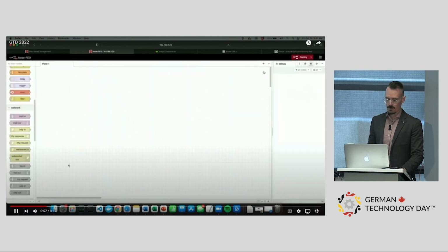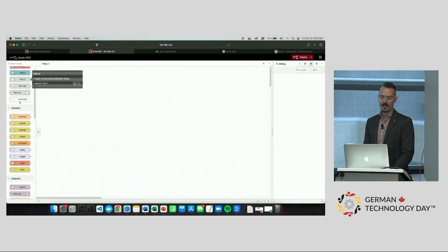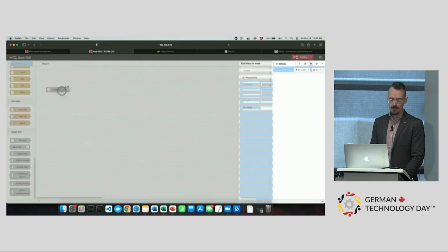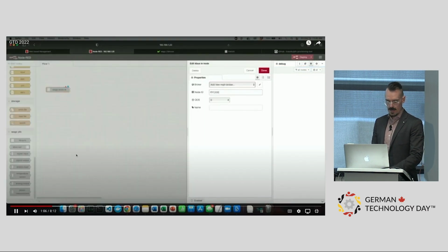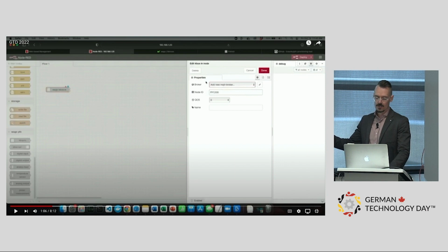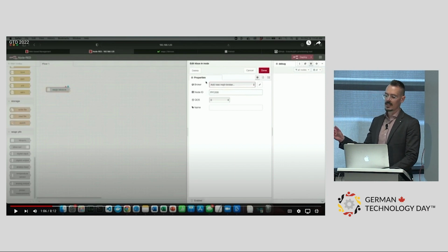So I've got this thing connected. I'm downloading the WAGO PFC palette. As I scroll down on the left here, you can see these WAGO PFC nodes. The first node that I have here is the WAGO KBus in node. And what that's doing is taking in information from the I/O bus so that we can do something with it. And it's via an MQTT connection on an MQTT broker that's sitting on the device.